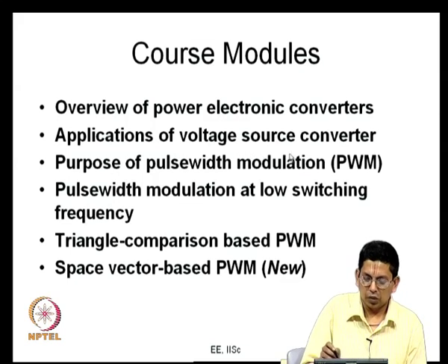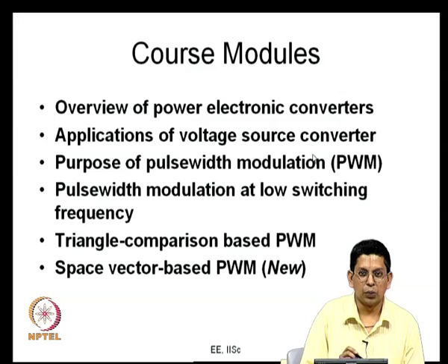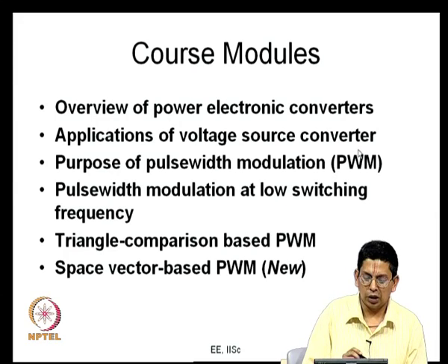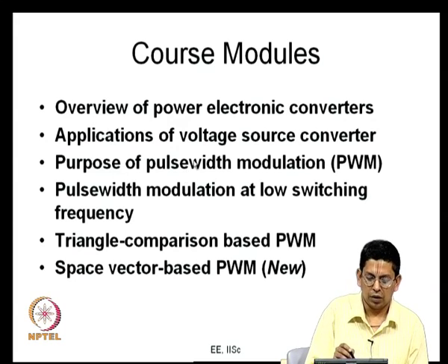Other than an induction motor drive, there are other things that you are going to look at. For example, we are looking at active front end converters, and power quality equipment such as static compensator, which you can use for supplying reactive power to the system. And further, you also use voltage source converters when you want to clean up the harmonics drawn by certain loads, that is harmonic filtering, active filters as they are called. So, these are the various applications.